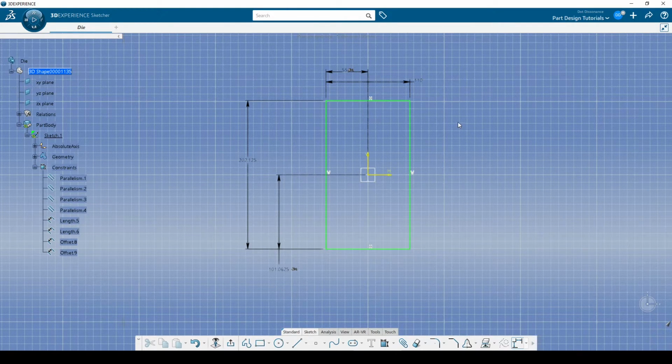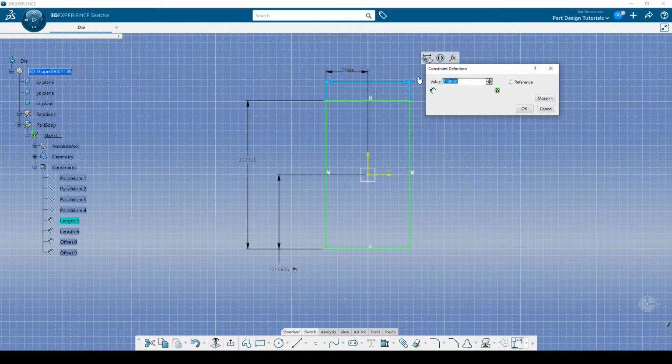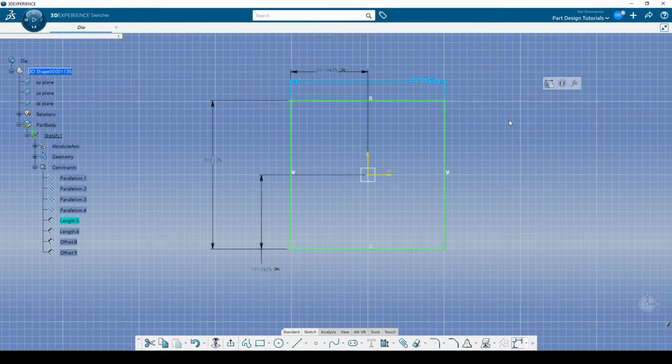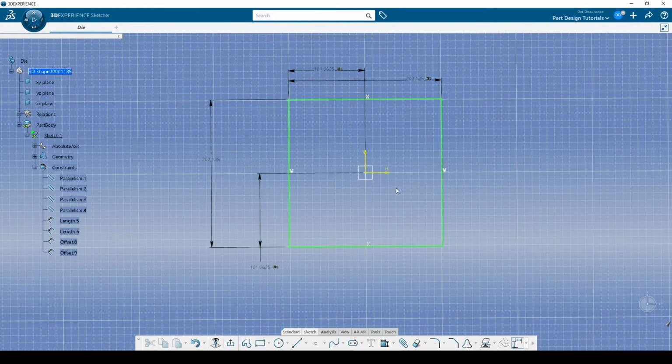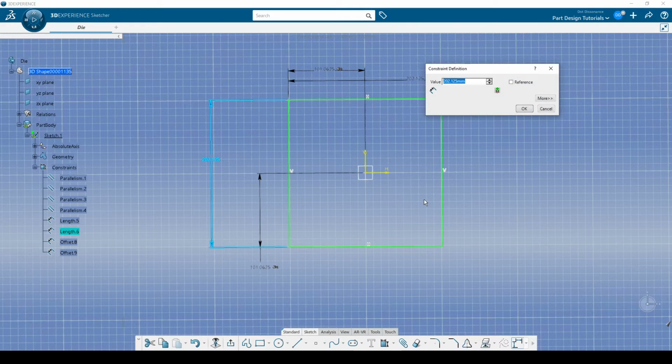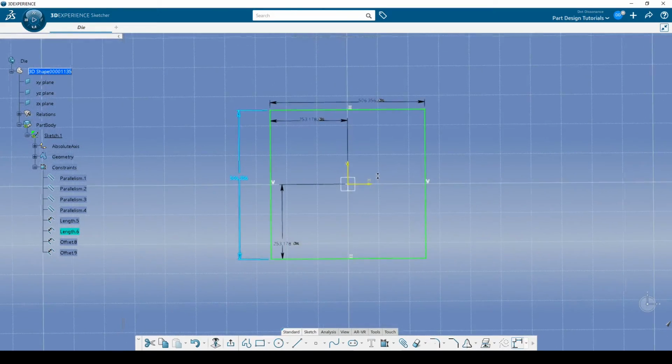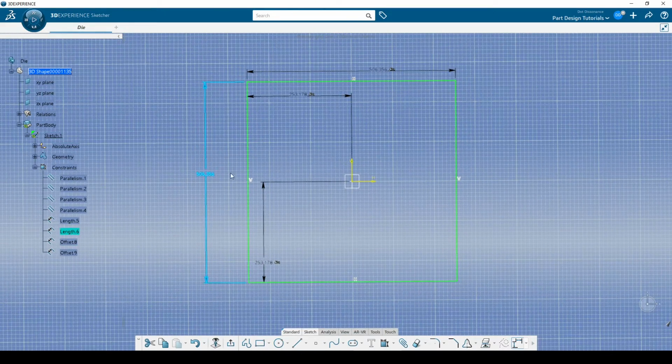And if they say, yeah, absolutely, they're always going to be the same, we might get bigger, might get smaller, but they're always going to be the same. Good, cool. So then what you can say is this dimension right here is equal to that dimension right there. And now we have a thing here that is always centered no matter what we do. So if I change this to 506.32, then there you go. There's our square. Okay. So that's a bit about formulas.